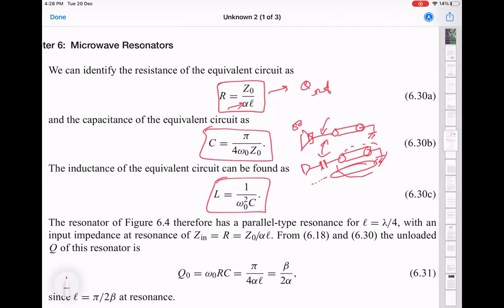Yes, the lumped element which I make in Microwave Office will be perfect, much better than any transmission line resonator. But this is basically the same point I've been saying all over this class, that you cannot make an inductor which has a fixed value of inductance and behaves exactly like that over a huge range of frequencies, particularly at microwave frequencies.